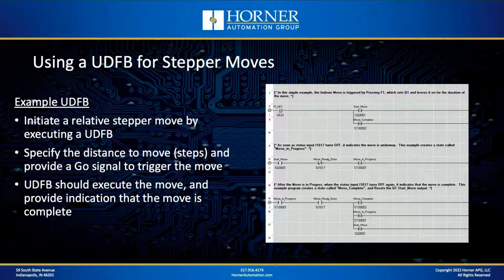Also, the UDFB should be waiting for a go signal to initiate the motion, and of course it should provide status telling us that the system has completed the move. Those are all the kind of things that I want to roll into this user-defined function block.